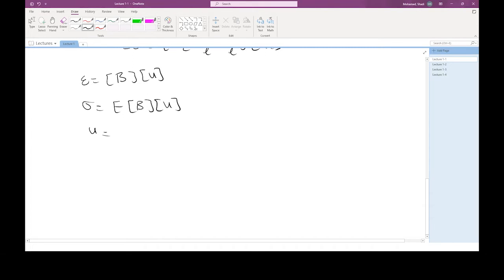And then you have u is basically 1 minus x over L multiplied with U. And this is basically the summary for what we have done in this first sheet. Expression for the strain, the stress, and the displacement, and everything is linked to the nodal displacement here. So everything is linked to the nodal displacement.